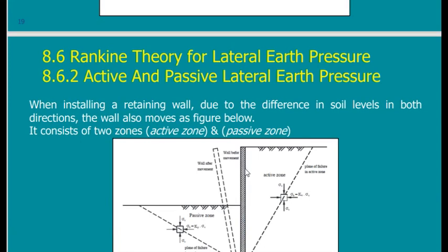You will tell me that because starting from this point, you will have an earth pressure here. It's not starting from the top. Yes, this is true, but there is another thing which is very, very important. In many cases, suppose that you have rain. Water will fill the crack.